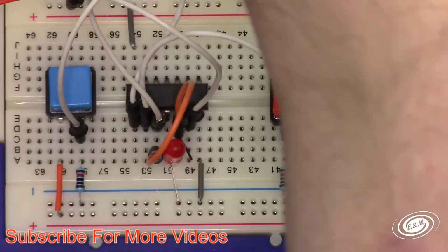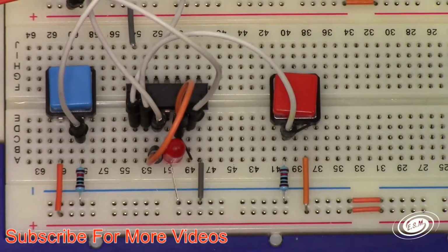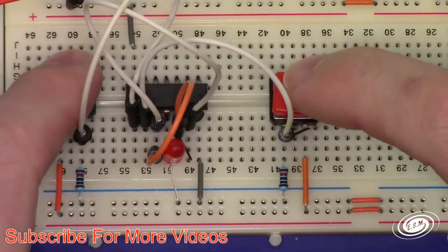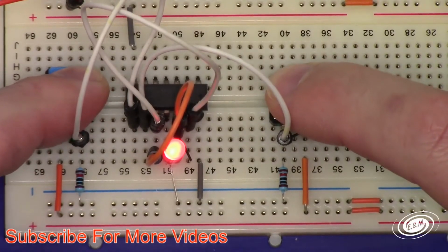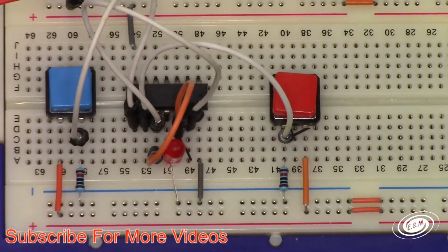Now if I turn this on, second NAND gate, I'm sorry. If I turn this on, you see the LED's off. If I press that, I press them both, it comes on. So I used 2 of these NAND gates to make an AND gate.